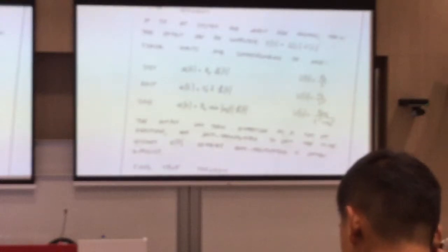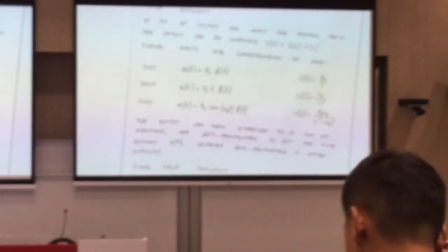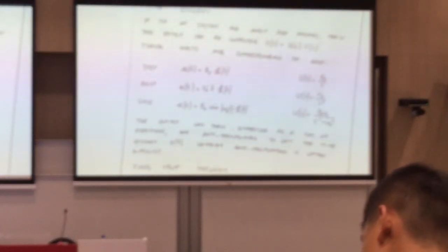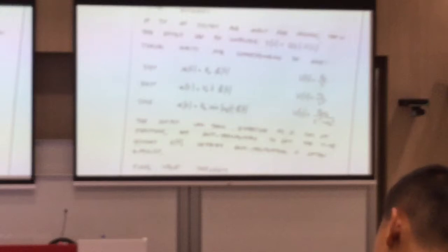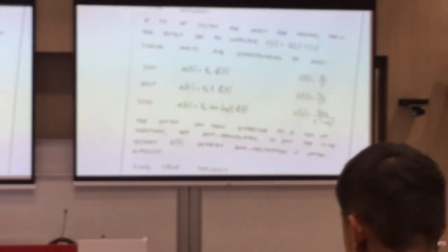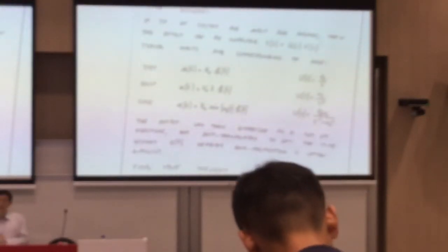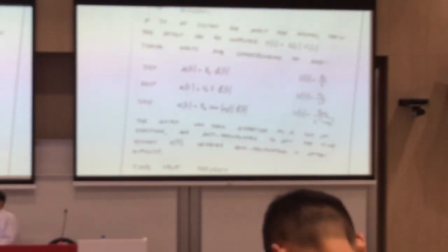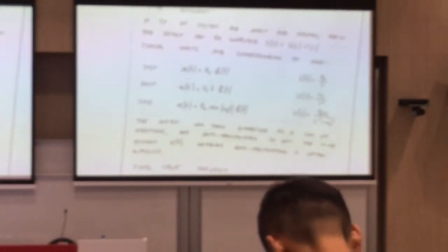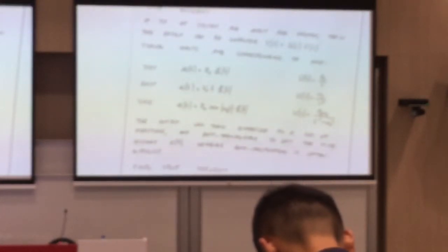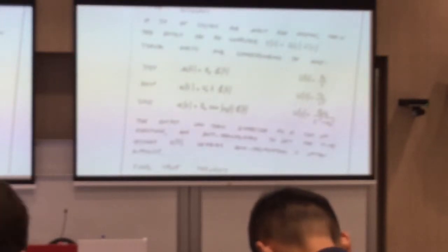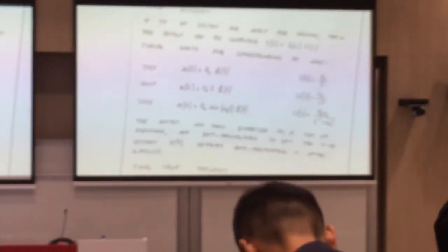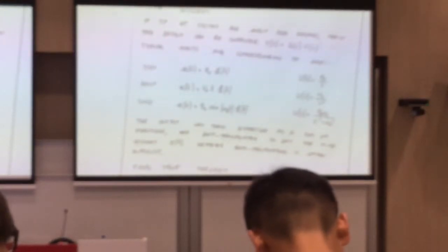So basically for dynamics, the purpose of the Laplace transform is to simplify your high order differential equation. And look at the control process. After you convert to the Laplace transform, you get your second order or other order polynomial function as a transfer function. You do not necessarily solve your differential equation. You do not necessarily know exactly what the function is for y, your position, right? But now you know your transfer function.